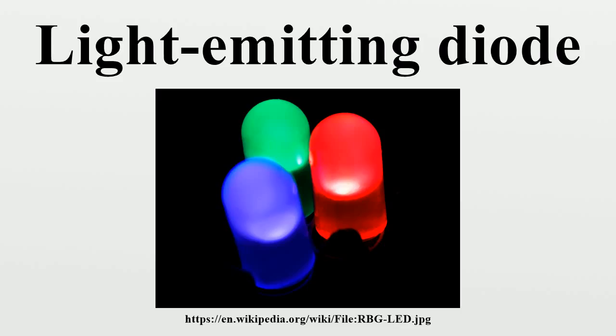White LEDs and the illumination breakthrough. The attainment of high efficiency in blue LEDs was quickly followed by the development of the first white LED. In this device, a Y3Al5O12:Ce (YAG) phosphor coating on the emitter absorbs some of the blue emission and produces yellow light through fluorescence. The combination of that yellow with remaining blue light appears white to the eye.